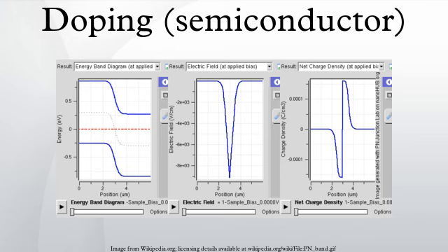Relationship to carrier concentration: for low levels of doping, the relevant energy states are populated sparsely by electrons or holes. This means it is possible to write simple expressions for the electron and hole carrier concentrations, by ignoring Pauli exclusion. Where EF is the Fermi level, EC is the minimum energy of the conduction band, and EV is the maximum energy of the valence band.